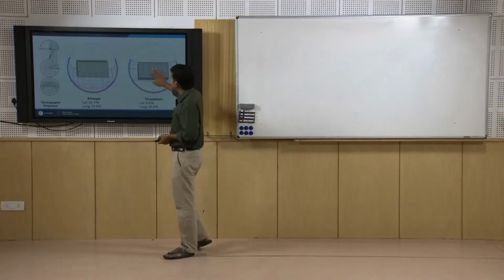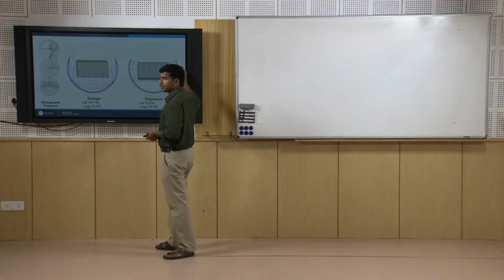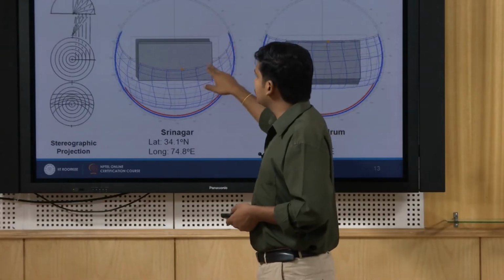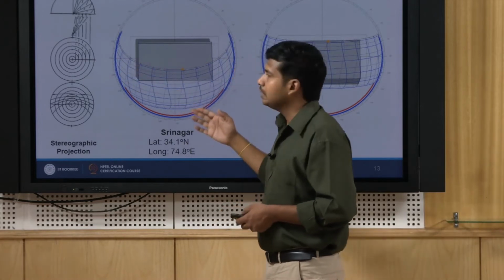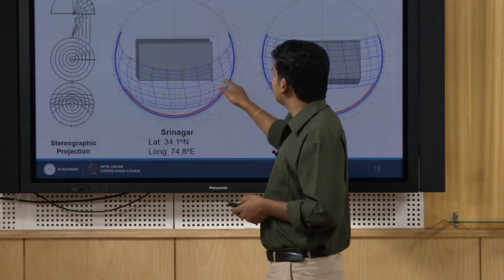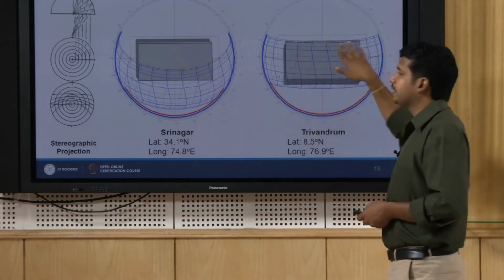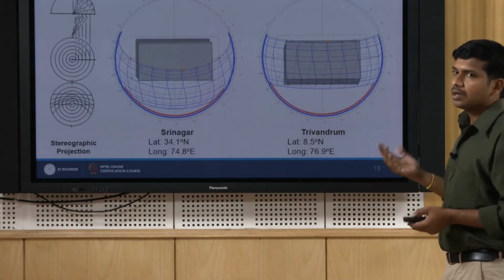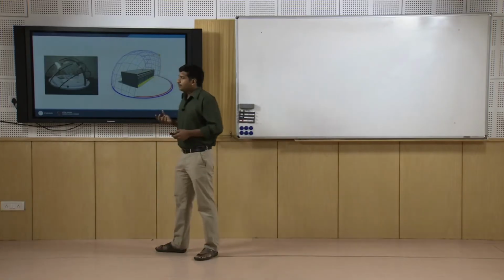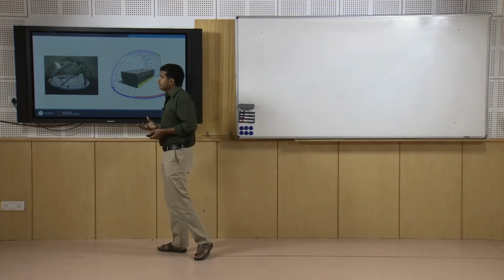So typically in this case your northern facade is going to have solar incidence for more duration, whereas here it is only for 2 to 3 months, that too slightly in the mornings and evenings, which can be prevented or obstructed through a vertical shading system. Here you will also need a horizontal shade on your northern wall in order to avoid direct solar radiation during summer. In laboratories this particular thing is studied using a heliodon.